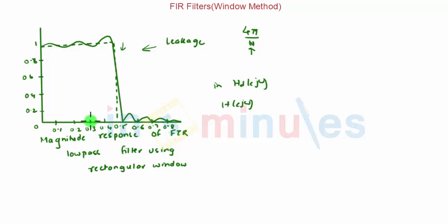These side lobe effects do not diminish significantly but remain constant as the duration of the rectangular window is increased. So we can say that whatever the value of HD of n included in H of n, the magnitudes of overshoot and leakage will not change significantly, and this is valid only when the rectangular window is used. This result is called the Gibbs phenomenon.